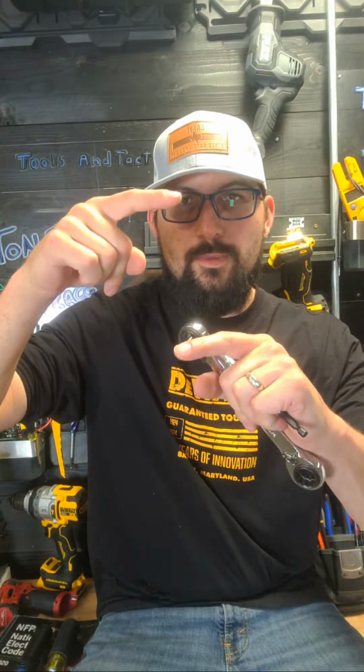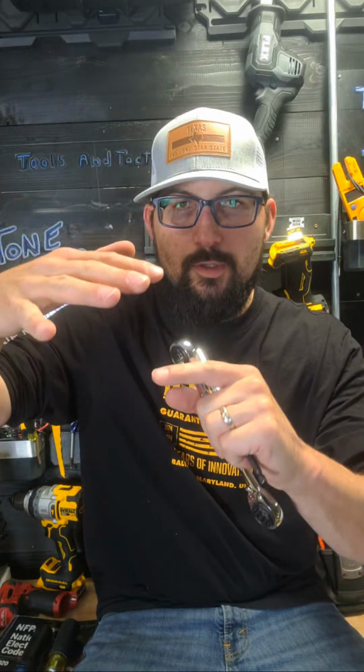So if you're putting it up in the angle iron, you had to know how deep the thread was going to protrude through the iron, before you sandwiched all your nuts and the washers together. And you had to know how long your angle iron below was, because you couldn't use strut at this job. You had to use angle iron because it was flat and able to be washed down. And we had to drill that, and we had a drill press on site. And you had to know all your measurements.